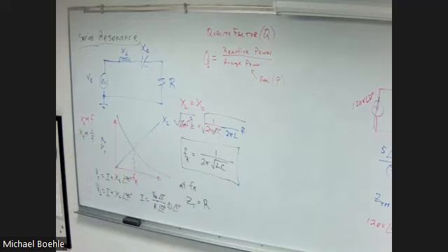Because this is a series circuit, what is the same for all these devices? Current, right? Components in series have the same current. Now, when this says reactive power, it does not mean the total reactive power in the circuit, because what is that?